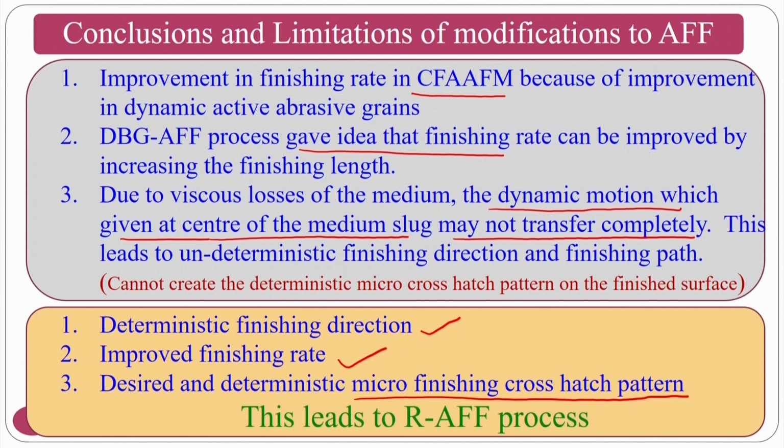In the previous condition, the motion is given to the medium, and the medium may or may not transfer this dynamic motion to the workpiece because of its viscous losses and elastic losses. If I can give the dynamic motion to the workpiece, then the workpiece will get the cross hatch patterns as well as dynamic motion, and the active abrasive particles will also take part in the finishing process.